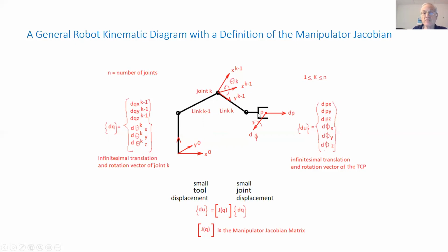And in order to find the accuracy at the point, for example, of a gripper of that robot as a function of the accuracies of each one of these links, what we do is we take the Jacobian of the relationship between the output position and the input position, the position of the gripper and position of the joints.